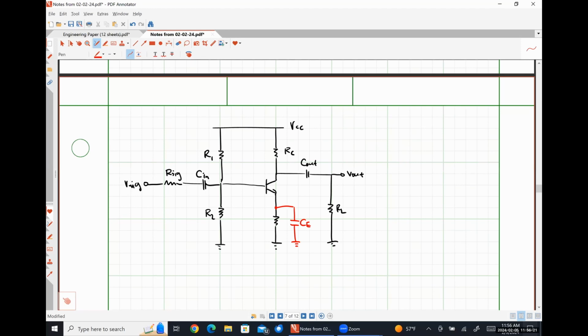But on the AC side of things, we don't see any of the downsides, so a reduction in gain caused by the emitter degeneration. We also don't get that increase in the input resistance either. A way to kind of split the baby, so to speak, is to actually split the resistor up into two different things. You guys have never heard the King Solomon thing of literally splitting a baby in half as a compromise? Read your Bible.